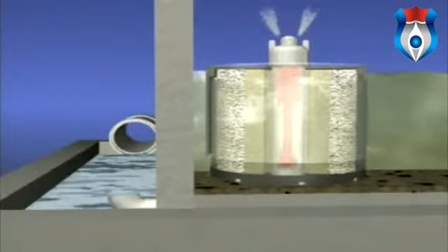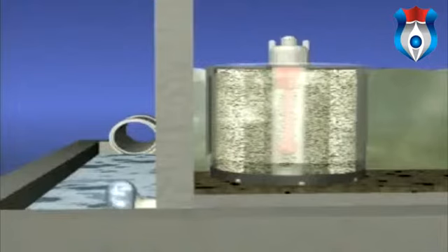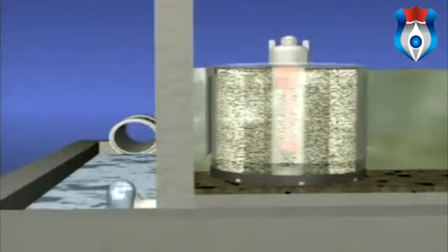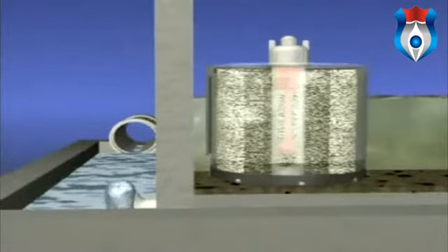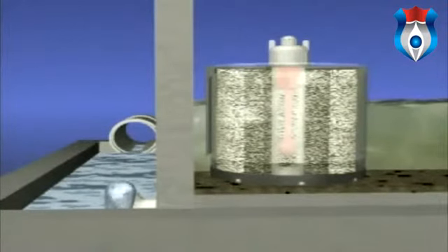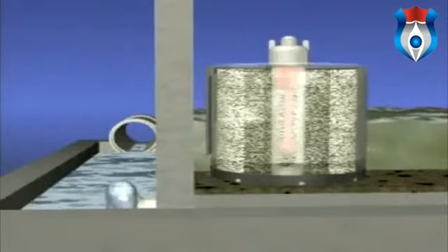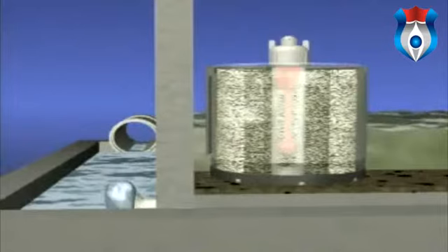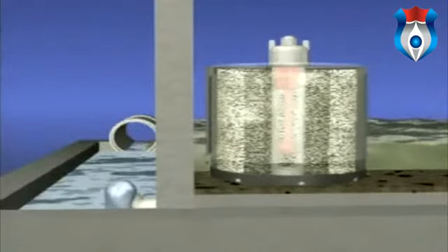When the water in the cartridge reaches the top of the float, buoyant forces pull the float free and allow the filtered water to drain out into the underdrain manifold for discharge. At this point, the air relief valve closes to create the siphon effect. The siphon increases the flow potential and distribution of pollutants across the filter media, increasing the effectiveness and useful life of the filter cartridge. The siphon effect continues until the stormwater in the vault begins to subside.